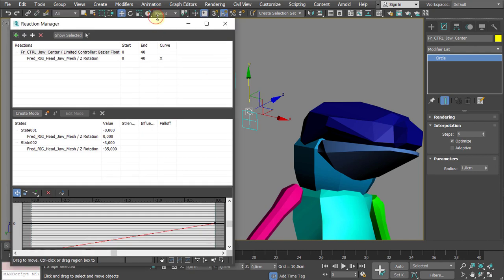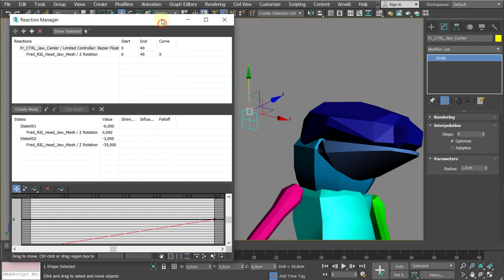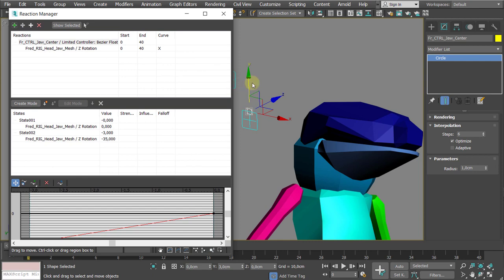Why? Because we have parent mode on, so we can read these values. And I don't have to add any more master because this master is already added. So the +3 and the -3 are the same y-axis master movements. The Z rotation is the same, so I don't need to add any new masters or new slaves.